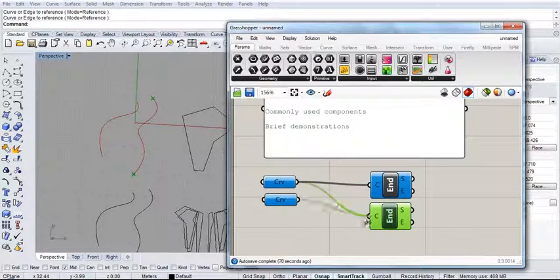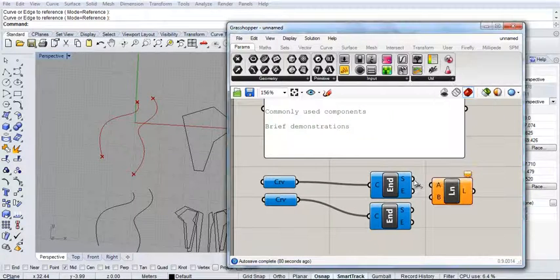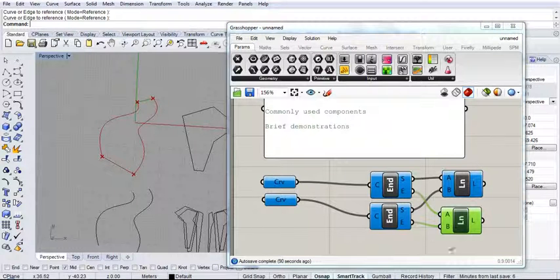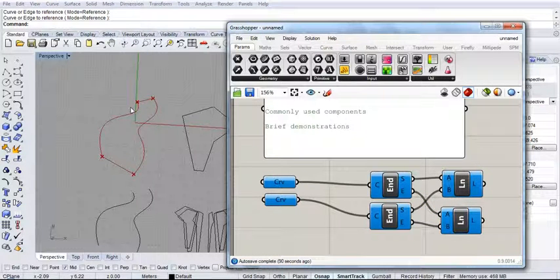So it'll give us access to those 2 points and we can start doing things with them. So for example, we might use it to really quickly close curves. So we have two curves defining edges, and we can use the endpoints to just draw lines between them to create a single closed curve.